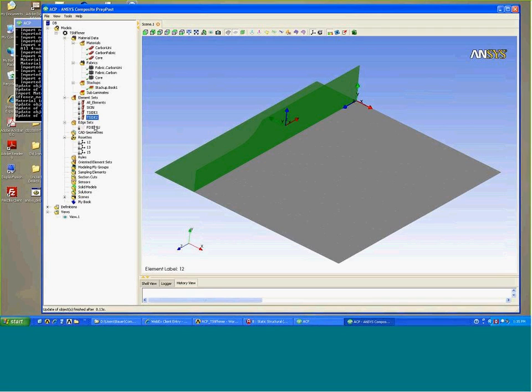I'm going to briefly mention edge sets, CAD geometries, and rules. Rules we'll touch on towards the end as a method of looking at regions for ply drop-offs and ply boundaries. When we assign plies to specific element sets and oriented element sets, this allows us additional control of where those ply boundaries stop. So I'll give an example of rules.